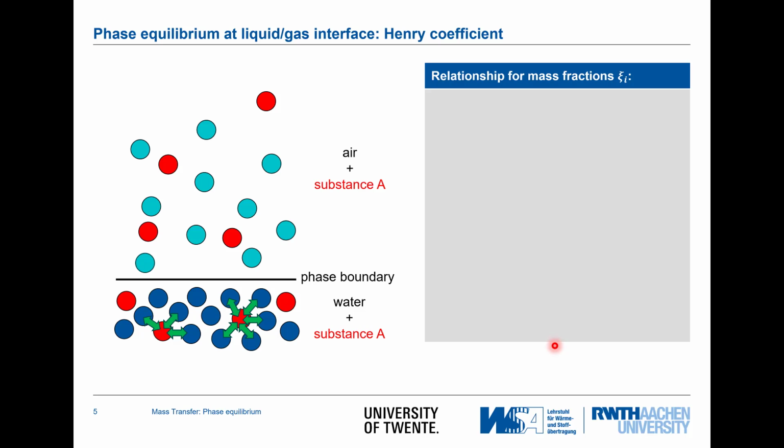If you want to understand how much mass is going from one side to the other, you have to look at the mass fraction, and we can, as I showed in one of the earlier videos, come from the concentration by writing it as the number of moles over the volume, number of moles then being the component mass divided by the component molar mass, and volume expressed as mass divided by density. We can come up with a relationship where we relate this concentration to mass fraction.